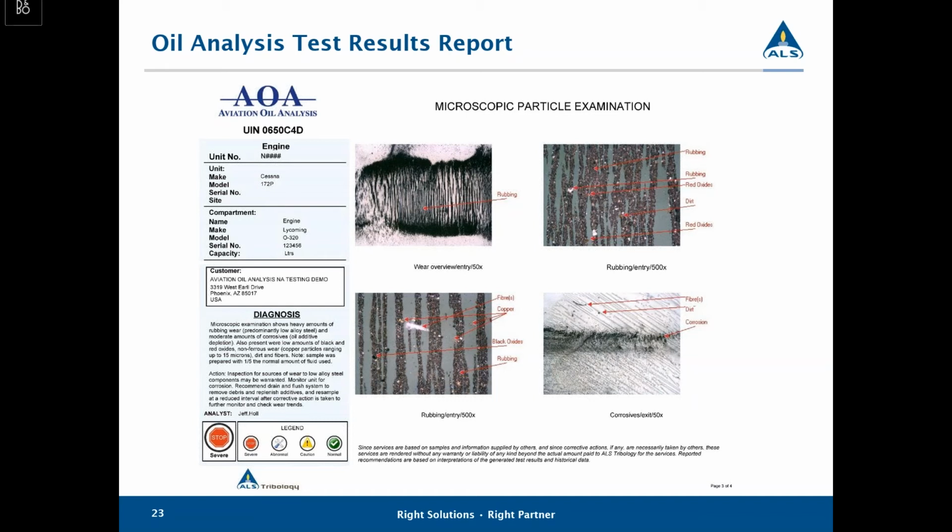So we use a special piece of equipment that makes the slide, and it has magnets to help align ferrous material. And you can see in the top left picture that it's in a vertical pattern. So you see a lot of up and down columns. Those are ferrous particles being aligned by the magnet. So it helps us know what's ferrous when we're looking at these particles. All the ferrous material will be in the columns, and anything that's non-ferrous will be distributed in between them. Our technicians will look at this under the microscope and identify what's going on.